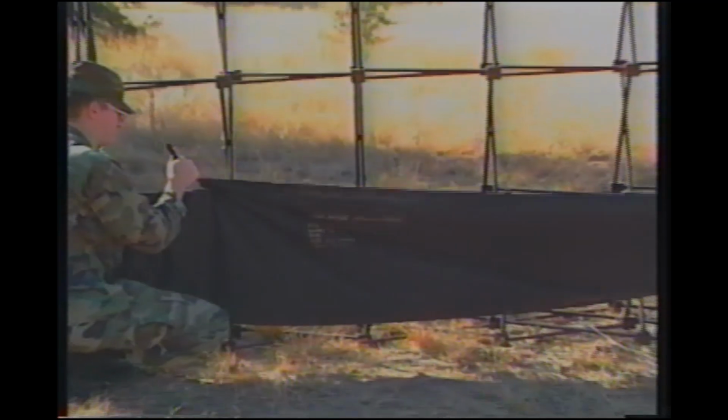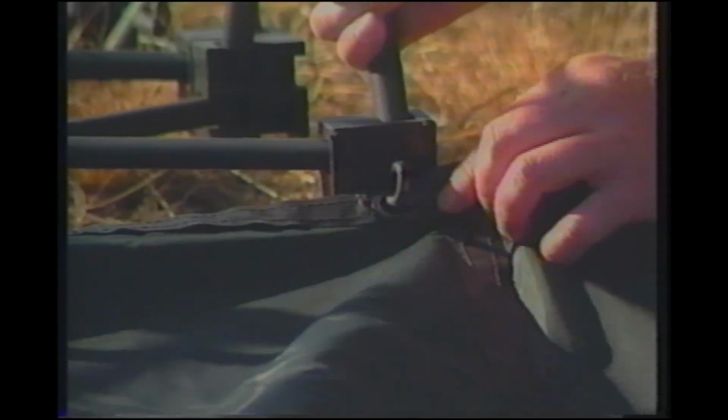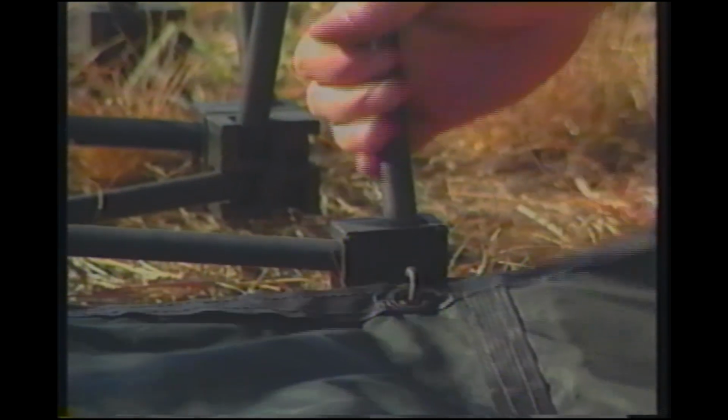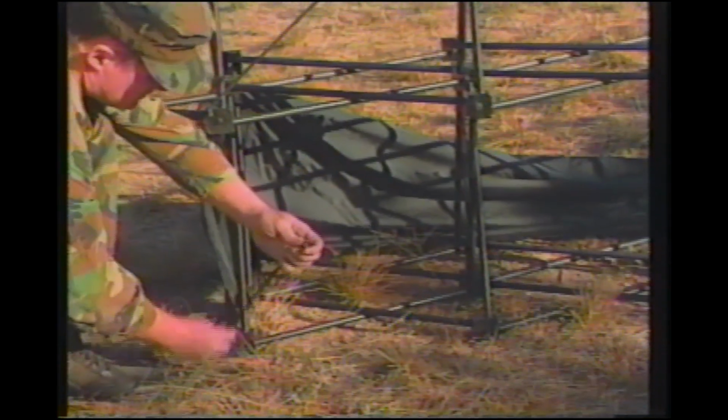Now, install the rear right side inside wheel skirt. You do this by hooking the 3 grommets at the bottom edge of the skirt to the hooks on the frame. Be sure to attach the stretch cords at the top edge and the ends of the skirt to the frame. Repeat this procedure to install the rear left inside wheel skirt.